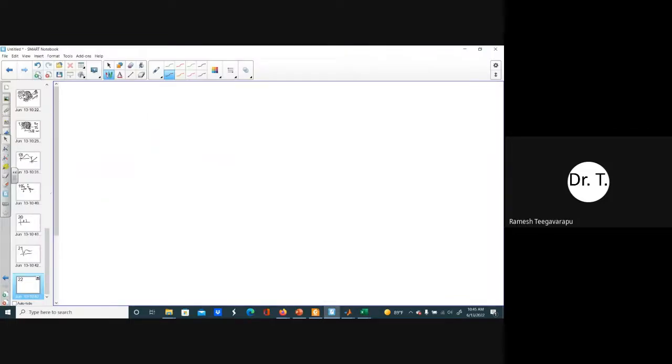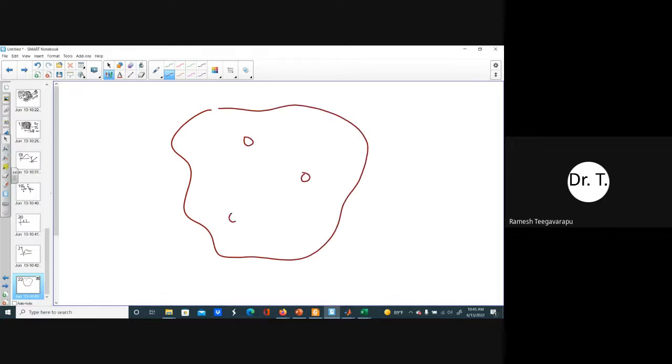So if you have, there are two issues in case of estimating missing values. So for example, this is your watershed, and then you have 1, 2, 3. If this is missing data, you can basically use the Euclidean distance. Let's say this is 2, this is 1, and 3. So this distance is d21, and this distance is d23. So you can actually use those distances, and then we can inverse those distances as our weights, right? The farther they are, the lower the weight is. So that's the whole idea of reciprocal distances.